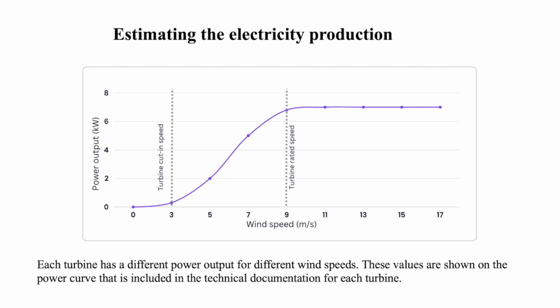It is also worth paying attention to the fact that when talking about the power of the turbine, we mean the electrical power, not the mechanical, and such criteria as turbine efficiency refers to how much mechanical power has been converted into electrical power. In order to calculate how much energy a wind turbine can produce in a month, we also need to understand what wind speeds prevail in our location.